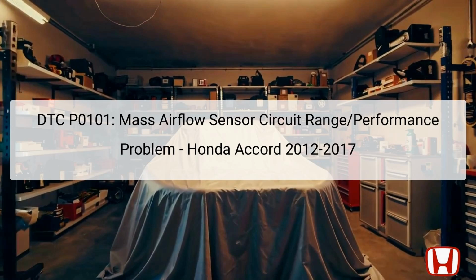The Diagnostic Trouble Code, DTC P0101, indicates that there is a range or performance problem with the mass airflow (MAF) sensor in Honda Accord models from 2012 to 2017, specifically those equipped with engine types J35Y1 and J35Y2. The MAF sensor plays a crucial role in measuring the amount of air entering the engine, which the Powertrain Control Module, PCM, uses to control fuel injection.